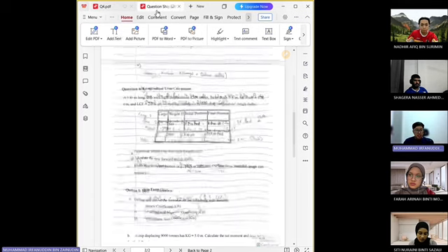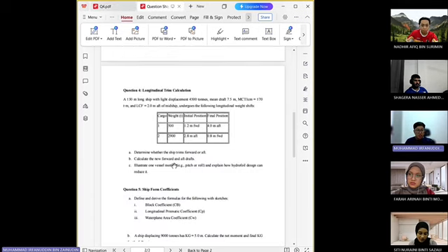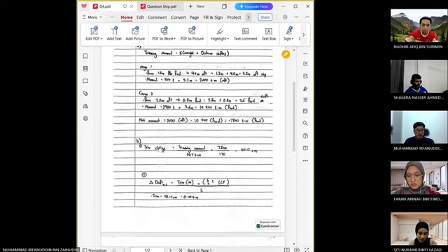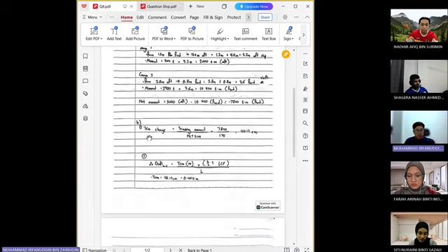Next, question B asks to calculate the new forward and aft draft. With the trim change formula, you use the trimming moments divided by MCT 1 centimeter, and you'll get 7,840 divided by 170, and you'll get 46.12 centimeters of trim change.